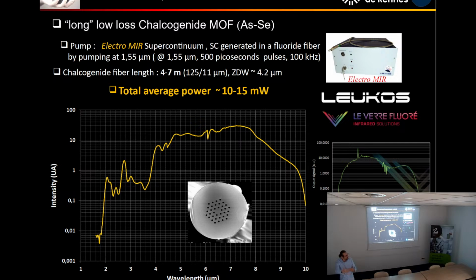So we believe that, in comparison with what has been obtained in silica, because now silica fibers can reach the transmission of a thin bulk of silica, in chalcogenide hollow core fibers you can reach 18 or 20 microns. Because for longer wavelengths, even if the light is propagating in the core of the fibers, the evanescent field will see the glass material, and after 18 or 20, the absorption is very huge, as in silica. Okay. I think we stop at this moment.